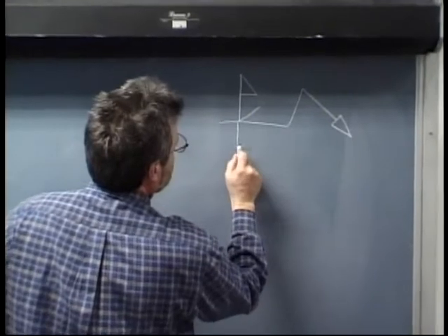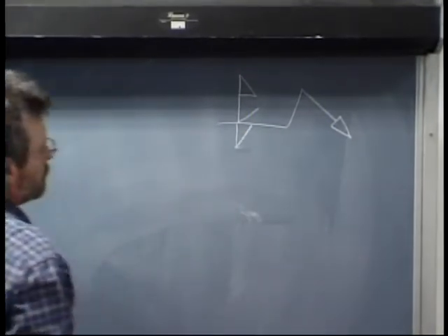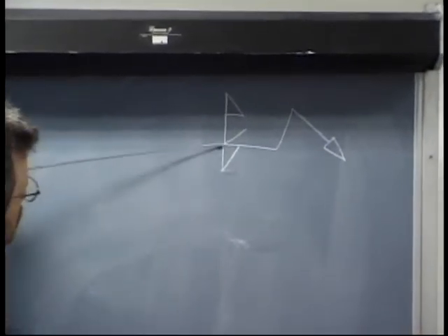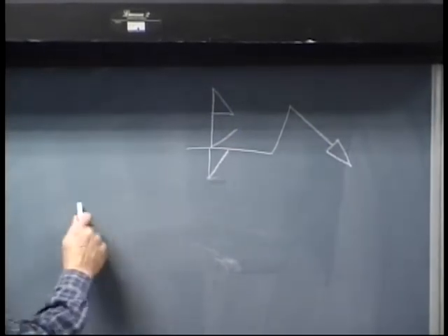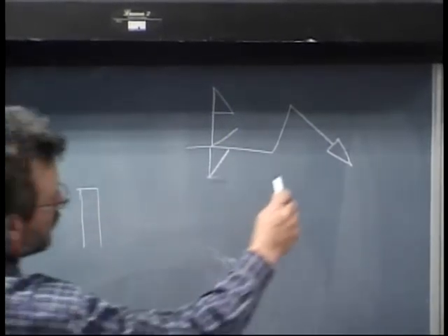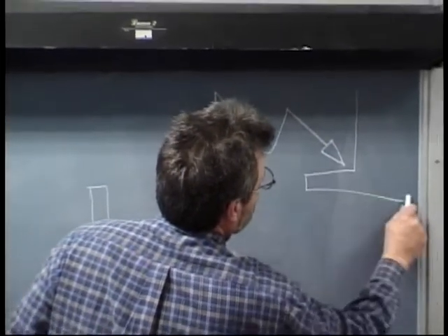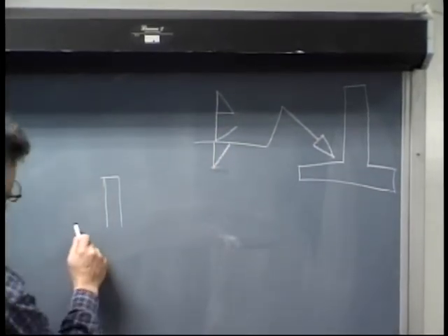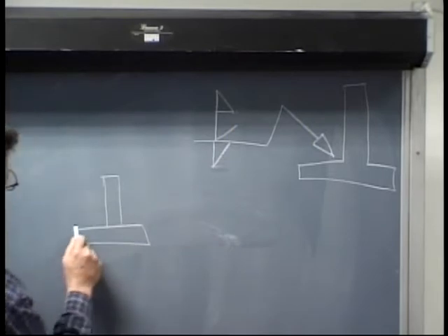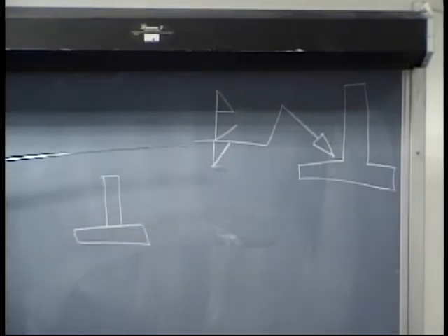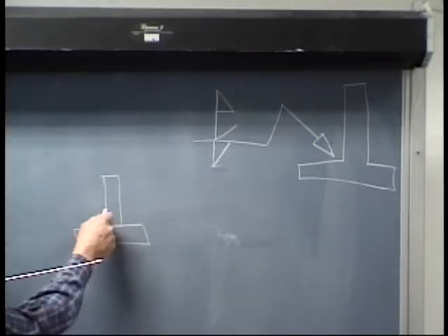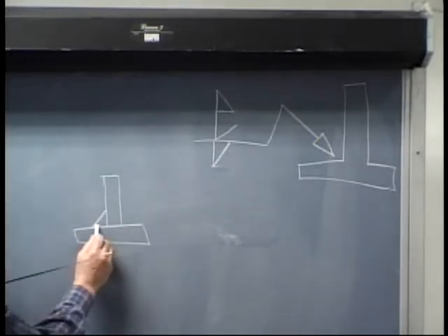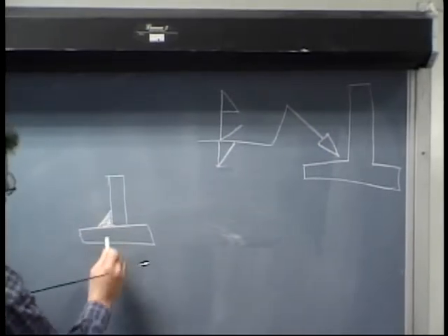Oops, my mistake. Okay, so we have a fillet weld, a single bevel, and a fillet weld. Well, that's probably going to be applied to a T-joint, like that. And so I'll come down here where I can make it a little bit better. So looking at our weld, we know that on the arrow side, which would be this side, we would want a fillet weld. Yes? Okay.